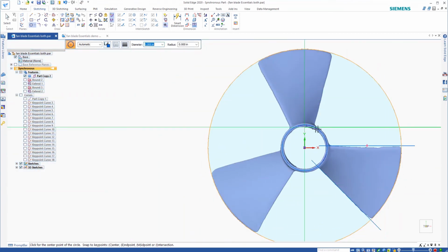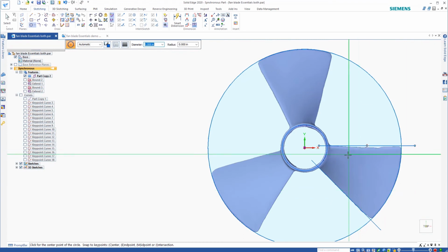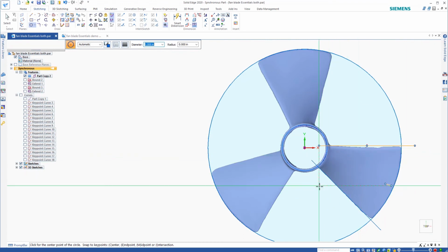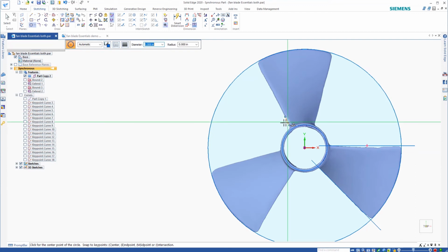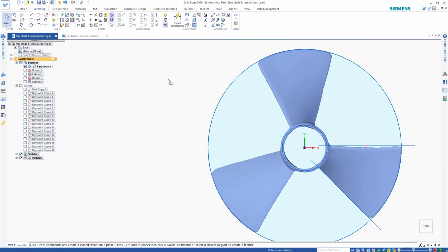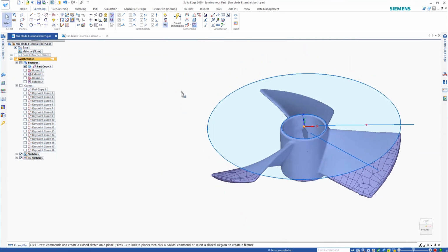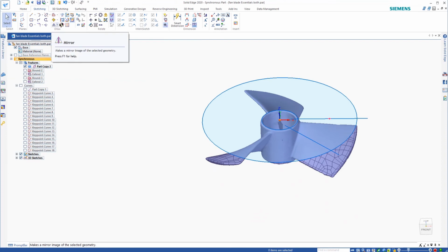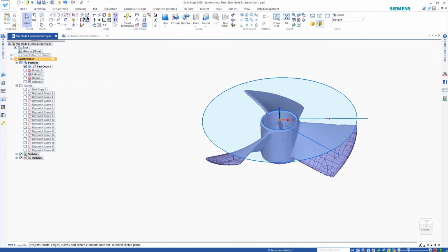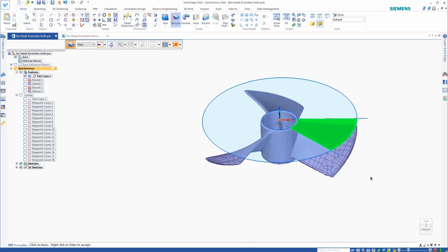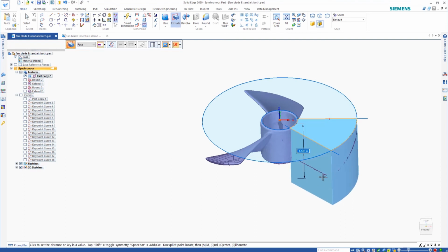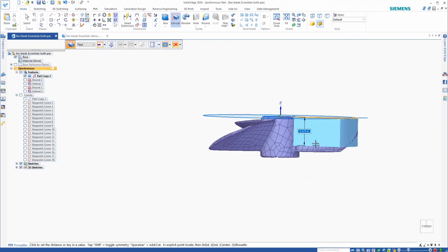So with Solid Edge, I don't have to necessarily trim all these pieces together. I can just rough out my sketch and then get out of it and then come over and do an extrusion just using that profile and select what loop that I want to use. So if I come over to click on this area right here and accept it, and then let's extrude this 1 inch.